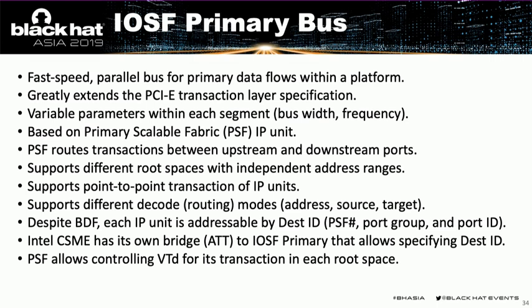Also, IOSF primary, extending PCI Express, supports different root spaces, allowing to isolate a group of devices with independent address ranges. These root spaces allow to isolate a group of devices from others.